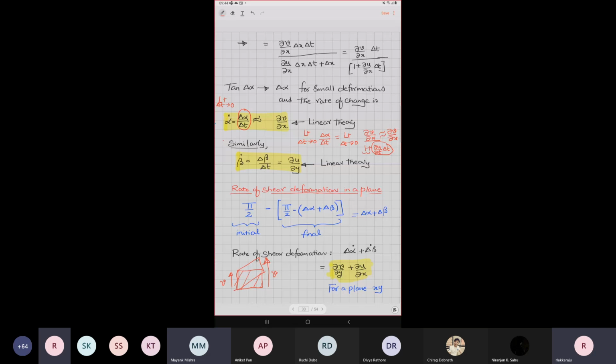The same thing one can ask even in terms of horizontal direction. You take a book in between your palms, move one of the palm with respect to other palm with a velocity. That's what you call shear. Based on how it is moving, one will be in a position to really talk about the shear rate of the system. And that is the way mathematically they try to quantify the angular deformation rate: del v by del x, where v is the vertical velocity component.